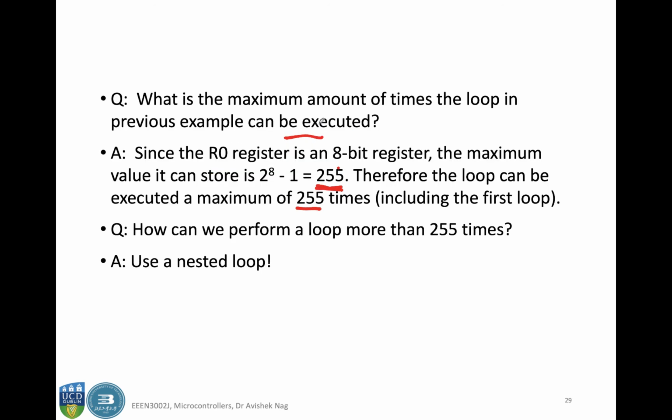So what if we need more than that? How can we perform a loop more than 255 times? The answer is, you can use nested loops.